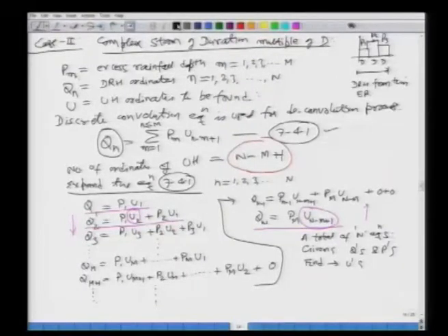So, you start from the top, you will have one unit hydrograph, you start from the bottom, you will have another unit hydrograph, and somebody else may pick any n minus m plus 1 equations from the middle. So, you will get another set of solution. So, you do not get a unique solution using this method. Why is that?